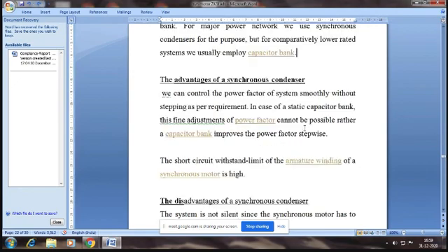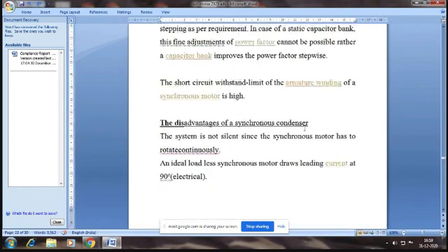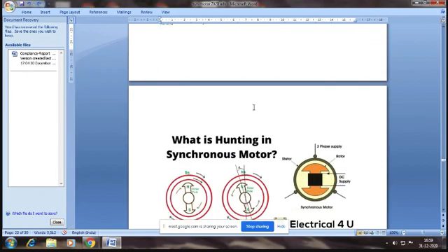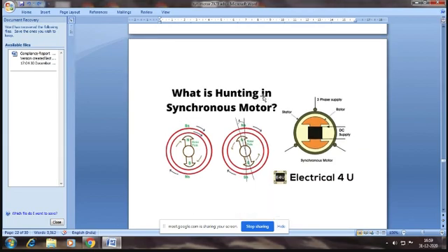That's all. And the drawback mainly is that this being a motor, a dynamic system, there will be continuous noise. So the environment will not be silent. Otherwise, the synchronous motor or condenser is a good technique to improve power factor. Okay, I think we'll stop here.